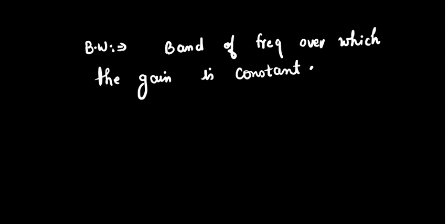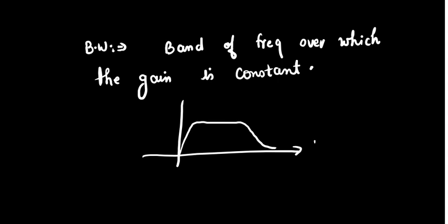And practically, if I ask you to plot the bandwidth, how would you do that? You will start with a sinusoidal signal of a small frequency, you will increase this frequency, right? And for every frequency, you will see the output V out, correct? V out divided by V in is your gain. So you will plot it and see, if this is frequency versus gain, it might be in dB. For this frequency range, the gain is almost constant, so the bandwidth of this amplifier is this.